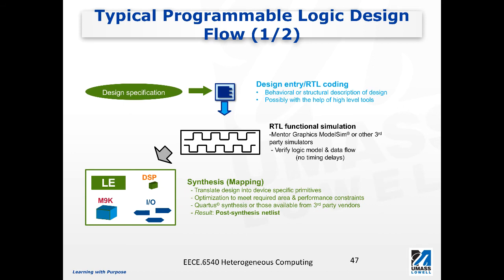After the design is verified functionally, then the tool can be used to do so-called synthesis. Synthesis essentially is to translate the design into the device-specific primitives. So at this stage, the tool will have a knowledge about the device that this design is going to be instantiated on.